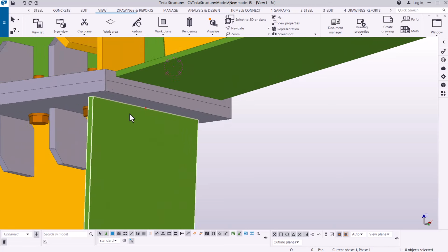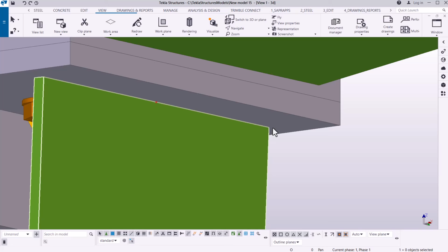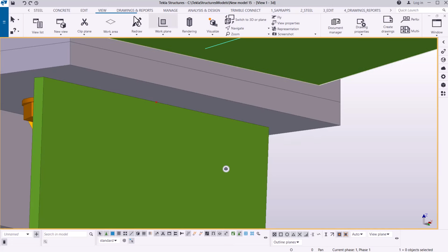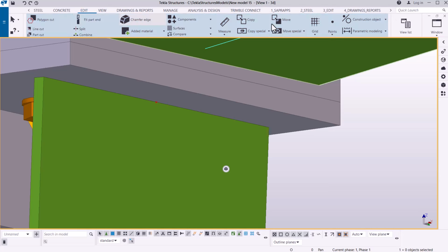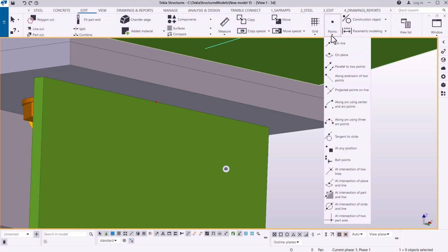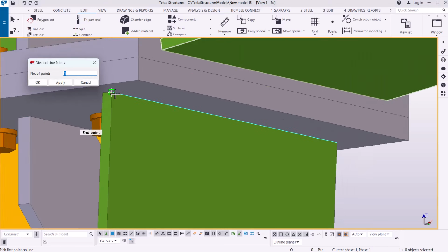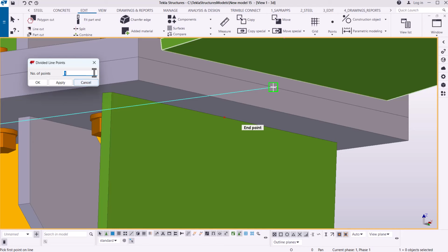Now, if you take a look here, I have a midpoint between these 2 points. And that midpoint I created very simply by coming to edit, then coming to point, clicking that drop down arrow, and I pick the first option here. The first option here, I wanted the midpoint. So for the midpoint, just pick that point and that point. So you'll get the midpoint of the 2 points that we've just clicked.